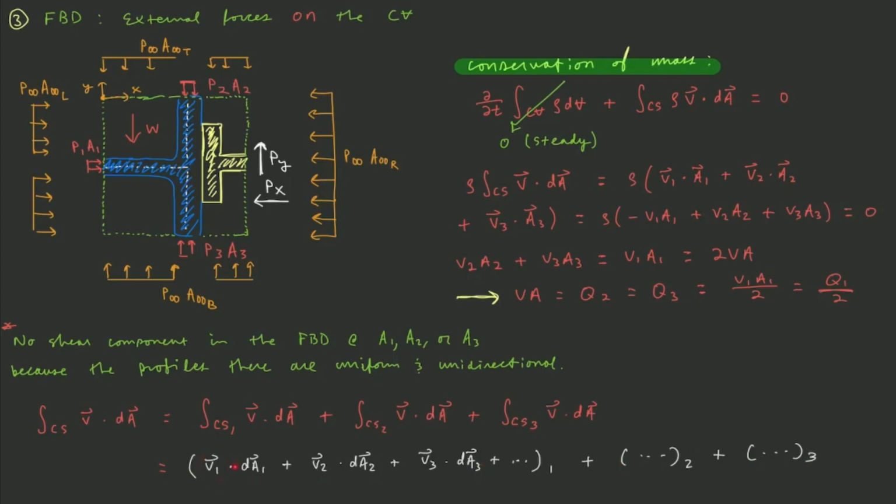So effectively you can pull them out of the sum, and then you have this v dot the sum of these dA vectors. What is the sum of the dA vectors? It is the area vector for that cross-section. So this is where you get your v dot A, because you're pulling out your velocities from this sum. It's this overall velocity dot the sum of these differential area vectors, which is equal to the overall area vector. That's how you're getting your v dot A's. It only works because our velocity vectors are uniform at each cross-section.